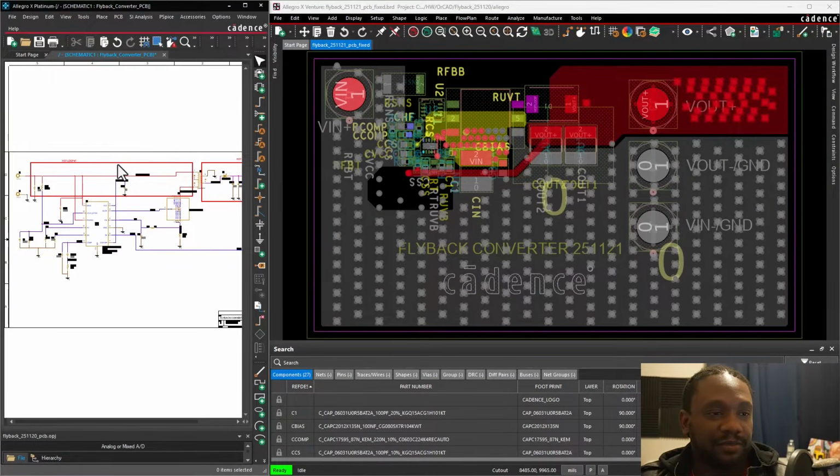The good news is that 80% of the fix to these problems is placing the components correctly. To do that, you need to place carefully for physics in the design. Don't worry, I'll walk you step by step through the physics of it so you can visualize what's going on. So looking at the schematic and PCB layout, watch how I cluster the parts. I bring them real close to each other to minimize the loop area.